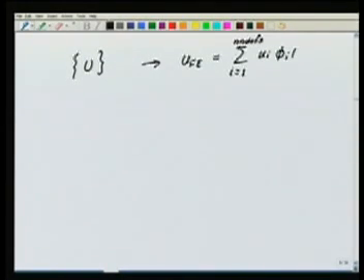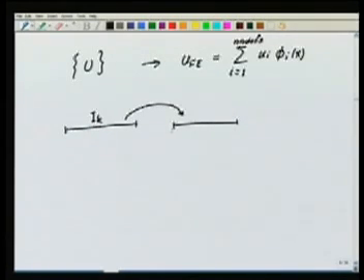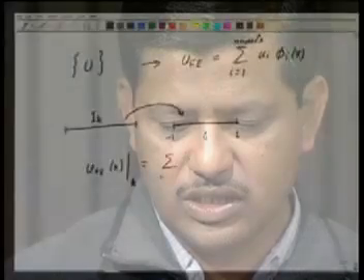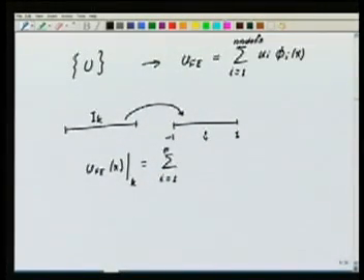anywhere in the domain, specifically in an element K. I can get the solution in terms of the master element coordinates. Okay. How? UFE at any point x in the element K is equal to sigma i equal to 1 to p plus 1, which is the number of nodes for the element, U_iG times N_i hat of psi, where psi corresponds to the x that we have taken.